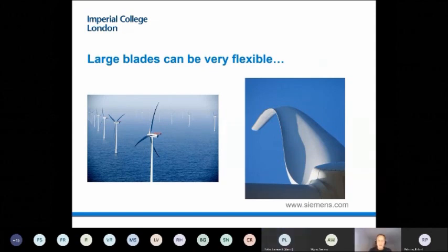The second reason they get larger is because the power, of course, goes with the area, but also goes with the wind speed. So the larger the wind turbine, the more power you get out of it. But then, of course, larger wind turbines are designed to sustain larger forces in general. So you would expect the cutout to move to the right and the velocities to move to the right as the wind turbines are larger by definition. All these are happening.